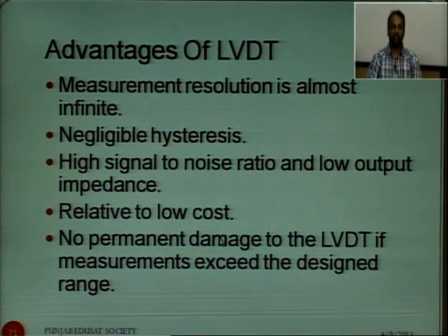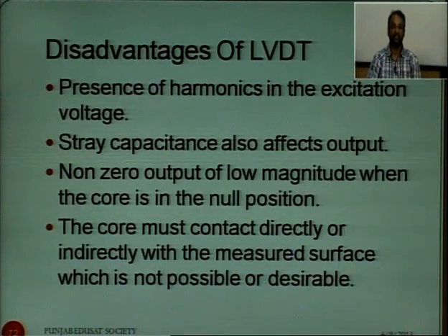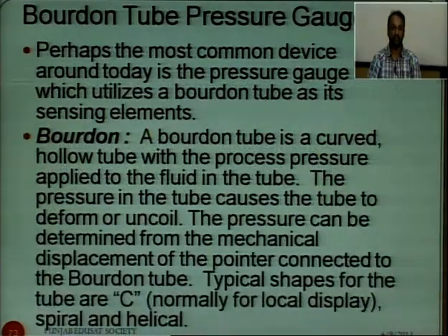Advantages of LVDT: measurement resolution is almost infinite, negligible hysteresis, high signal to noise ratio, low cost, no damage to the LVDT. Disadvantages: presence of harmonics, stray capacitance also present. The core must contact directly or indirectly with the measured surface, which is not always possible or desirable.